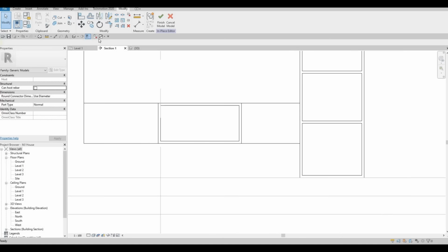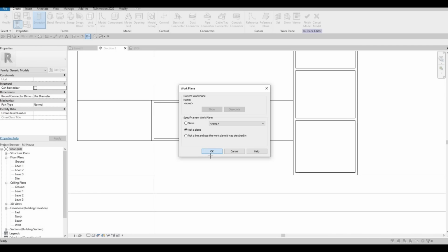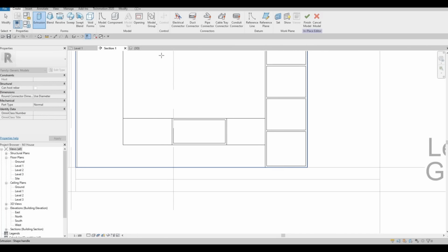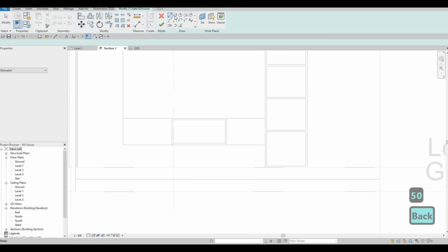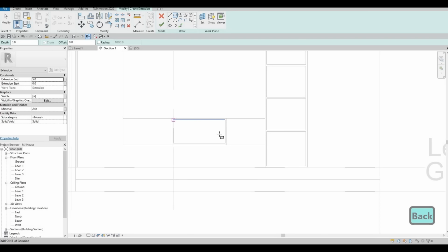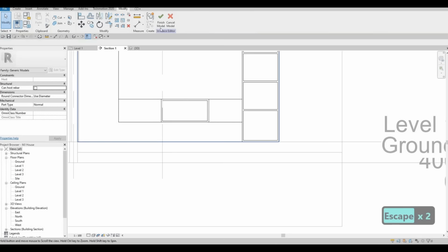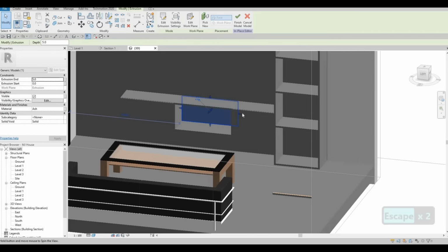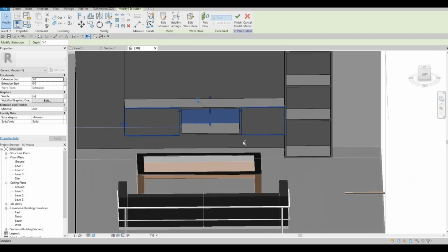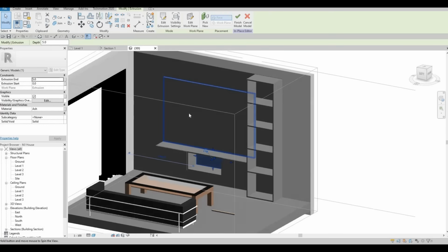So I'm just going to create an extrusion again and then pick a plane, which is this wall, and then here just 5, not 50, just 5, and then it's just a backing right here. Click on finish, and I'm happy with what we have done there. We have a backing there now that is the same material. So once we're in Twinmotion, once we add the material, it will look like that as well.